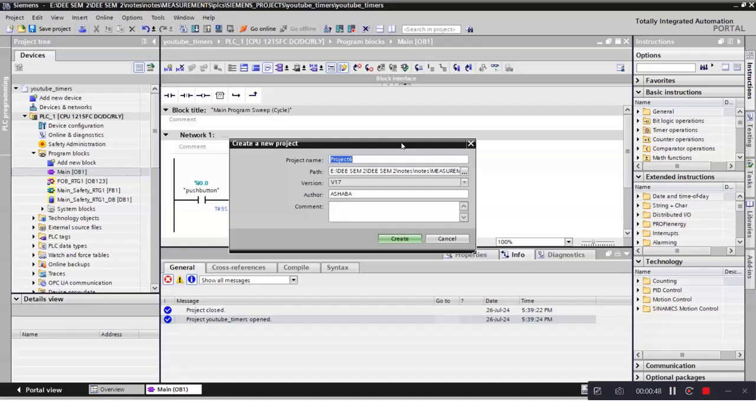Remember, this is done in automation, of course, to minimize human intervention. So you need timers to count or to switch on or to energize a particular circuit and have a particular event take place when it is desired to be energized, and then be de-energized when it is desired. With the help of timers and counters, you are able to design such.